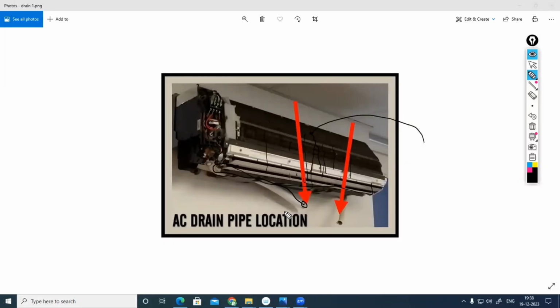All these condensate drain pipes, we can club with the rainwater harvesting system, or with the irrigation tank, or outside we can provide a soak pit. There we can free discharge to the atmosphere, depends. But if you are using this water, condensation of water from the atmosphere is like rainwater. It does not have that much contamination. That is pure water only.